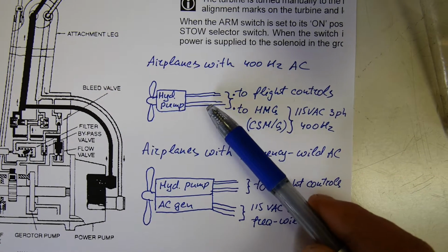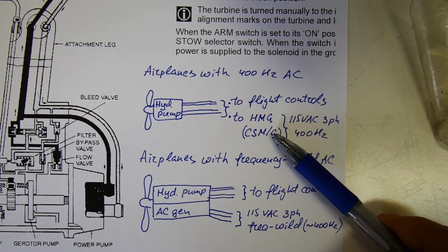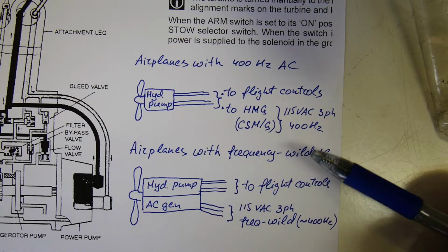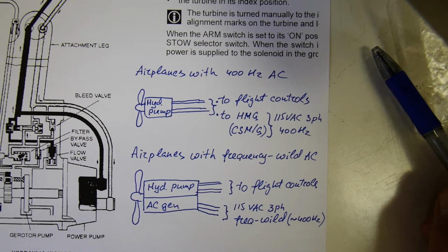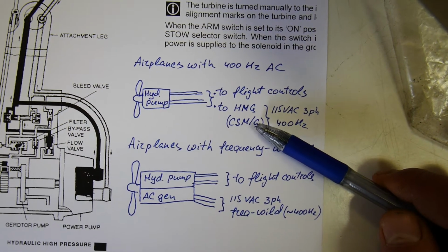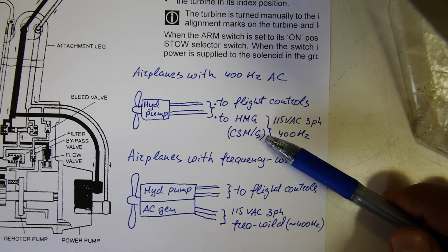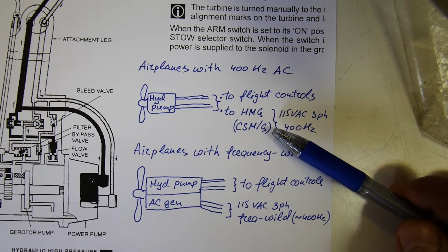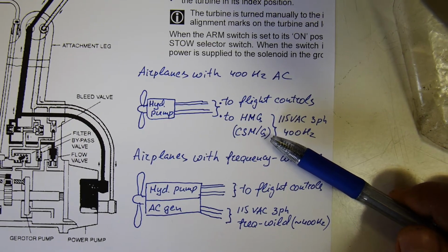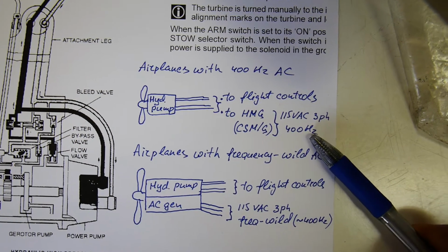This device takes hydraulic power and rotates its hydraulic motor. The speed of the hydraulic motor is controlled very precisely, and therefore this motor drives its own built-in generator, which operates with exact speed, for example 12,000 RPM, and so it is able to produce constant frequency.